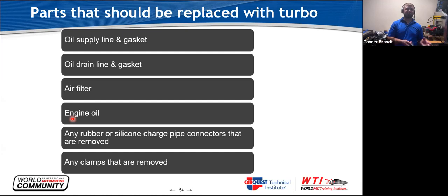So just replace them, do yourself a favor, especially if you're working on diesel stuff, because when they do crack, if it's on an ambulance or something like that, you don't want to go down that hole. So just replace that stuff on every single turbo. Everything in this list, just do it, quote it in the job, be done with it.